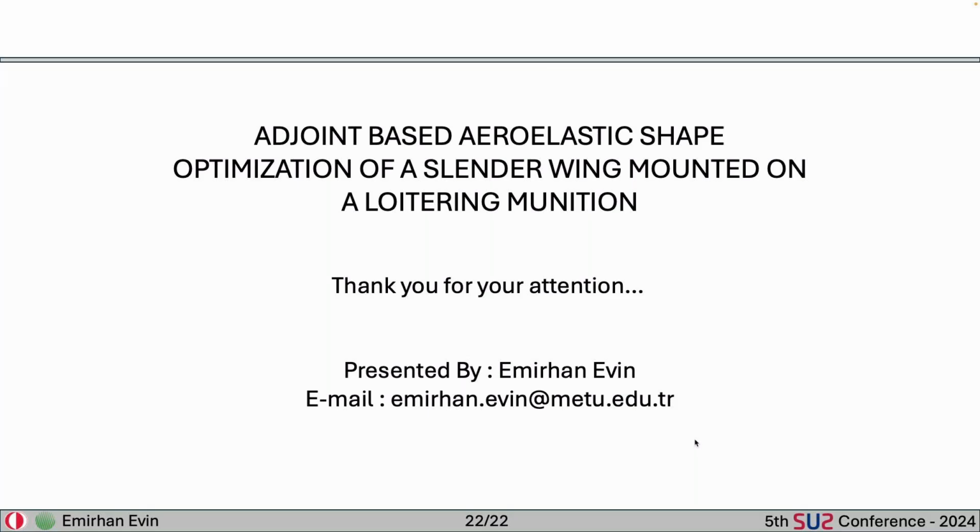Yeah, but in Pointwise, you can use T-Rex also on the surface. So for the leading edge, maybe it will lead to a lower number of points for the grid, and can help at the leading edge also. I wonder if it was just needed or not to use isotropic. It's not needed. I can try. Okay.